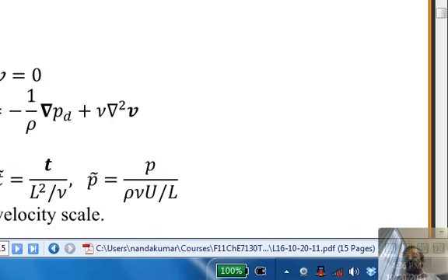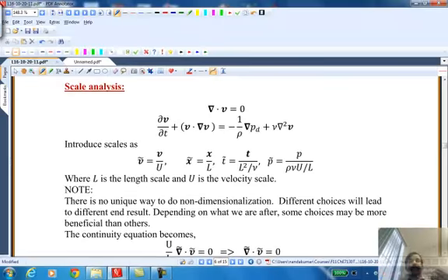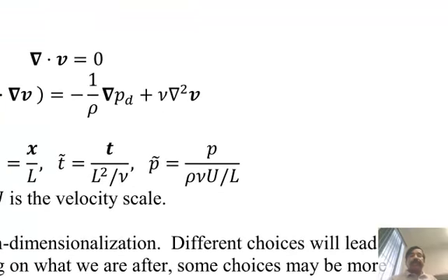Now, we are going to go back to the full Navier-Stokes equation and do a scaling analysis to see how we can get rid of this term. So far, we have been getting rid of that term by assuming the flow to be one-dimensional, rectilinear flow, where that assumption knocks off that term identically. And then the equation is linear, we can get a solution. But once you go into the two-dimensional flow, that term will not be 0 identically. But we have to identify when will that term be small compared to other terms. So this is the scaling analysis.